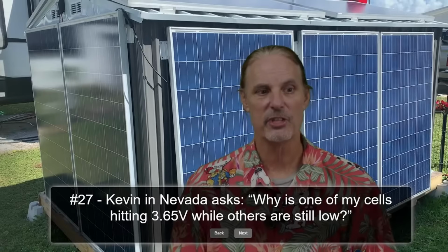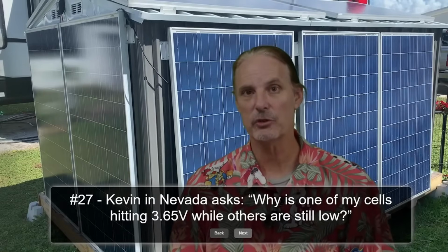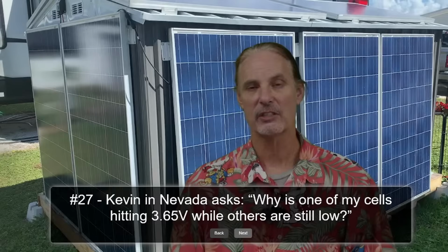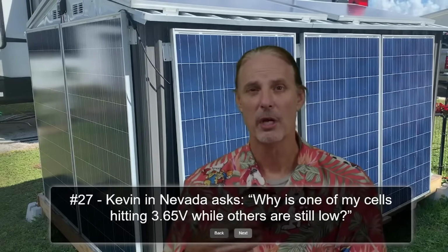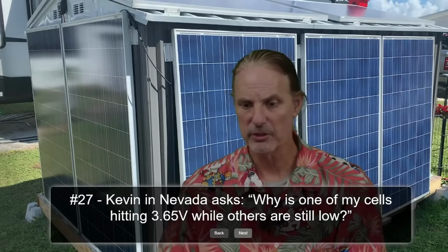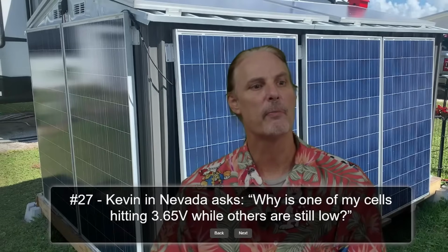My guess is that you're trying to charge too high too fast. The easiest way to work this is to start with a lower voltage and give the battery time to balance a little bit, and then you can handle it from there.